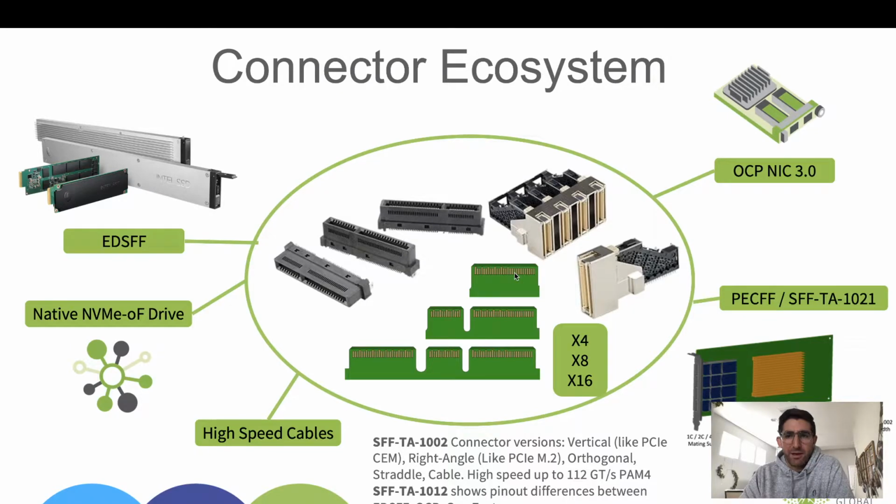What you're seeing here is the orthogonal connector, which was really developed to be a low-cost solution for hyperscale and one-use servers, where you can actually route the PCIe lanes directly from the CPU out to this edge connector and do it without expensive cabling or PCIe switches or retimers or link extension devices. So that allows for really low-cost attach of NVMe devices.